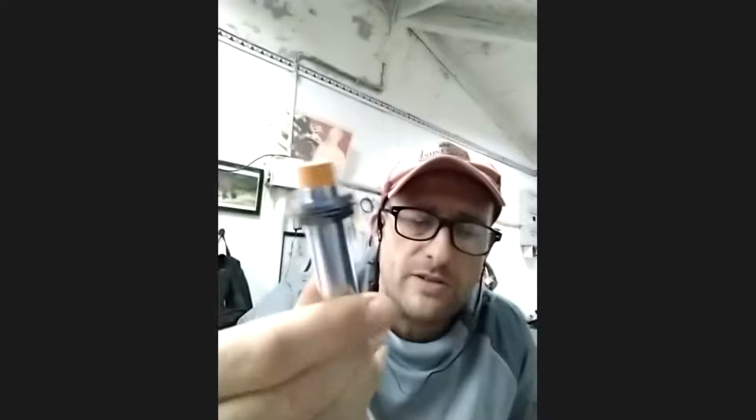Well, that's all. This is a very common sensor. They use it for the 3D printers and that kind of thing. But the tractor got one very similar, but with 3 wires, and you hook up 2 of the wires to the battery, and the other one is the wire that gives you the data. So you don't have that kind of problem, but you have to put some resistor to cut out the noise that the sensor brings.